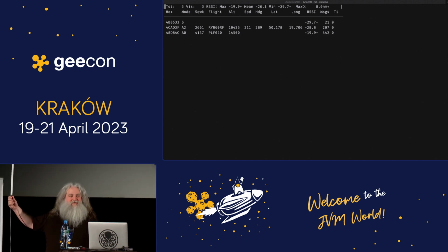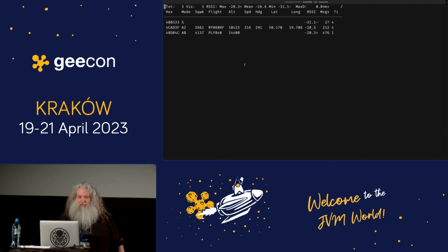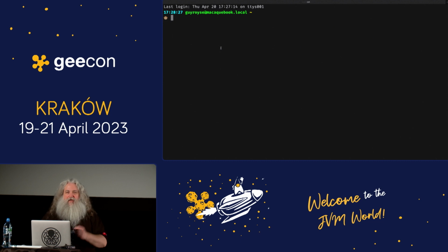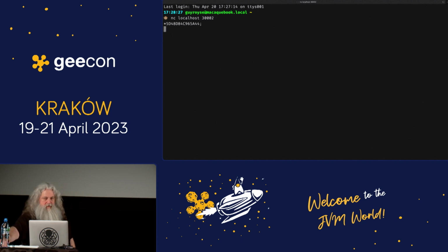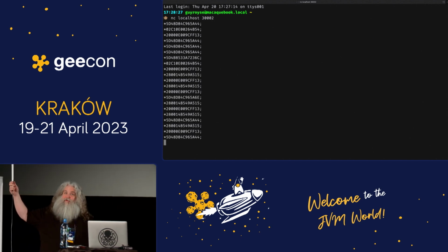So this is kind of neat. I'm going to set this down and show you what this will do behind the scenes. This is still going to be running. What Dump 1090 does is it listens on ports 30001, 2, and 3. On 30002, it will publish hexadecimal information that it's decoding. So if I just use netcat, localhost, 30002, and I hold this up, this is what the hex coming over the signal looks like.